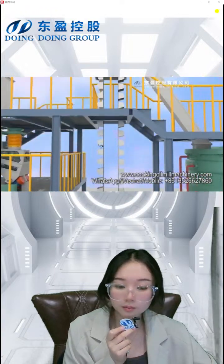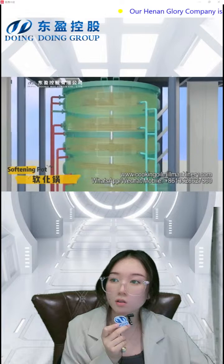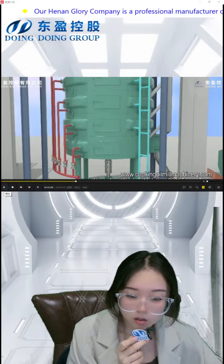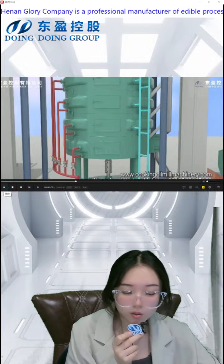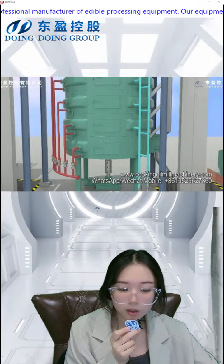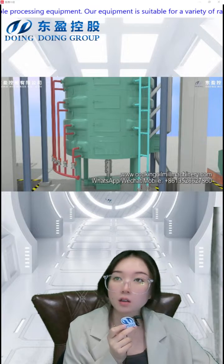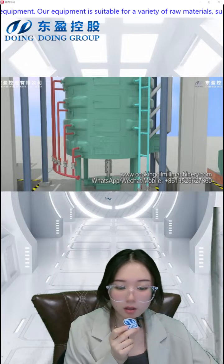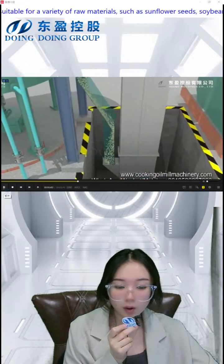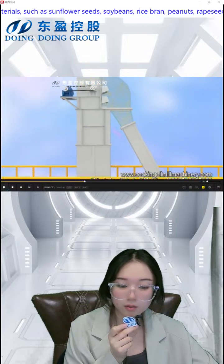The crushed materials go through the bucket elevator into the softening pot. Direct steam is introduced to adjust the moisture and temperature. Normally, after softening, the moisture is maintained at around 10%, and the temperature is maintained at around 70 degrees. The temperature and moisture need to be adjusted for the different raw materials.